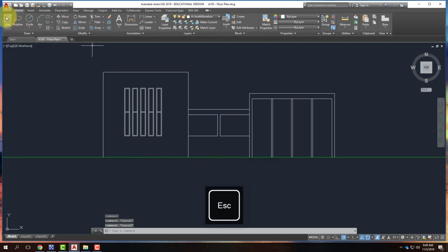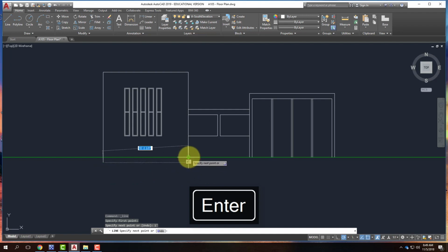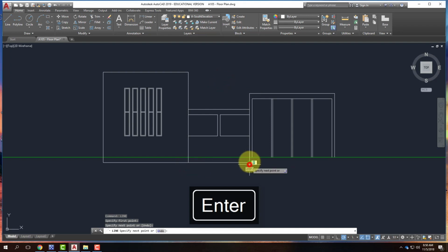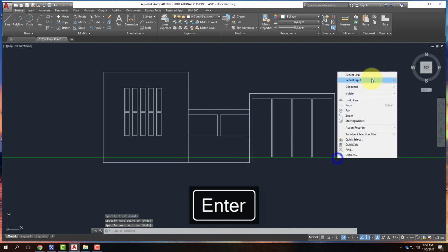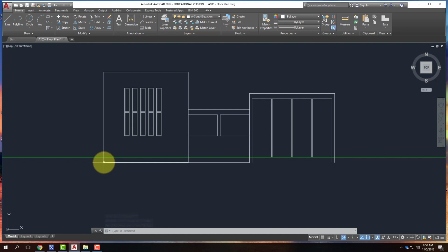And I'm going to suggest that you come in and you draw a foot down and across to represent the structure of the building. And my building gets a little weird because it has these little wing walls sticking out. Like that. And then below this, I would encourage you to use the ground plane at 8 inches below where that is. So I'm going finished floor down a foot to end the building, and then another 8 inches down before the ground happens. And that's because you typically have a little bit of foundation outside of your building.